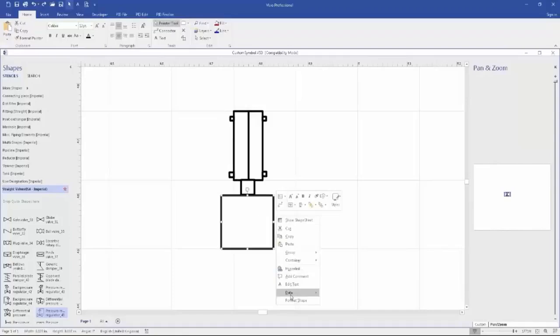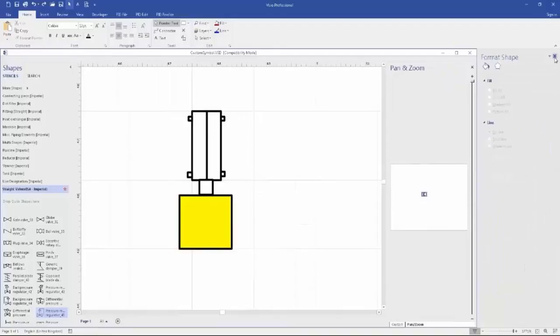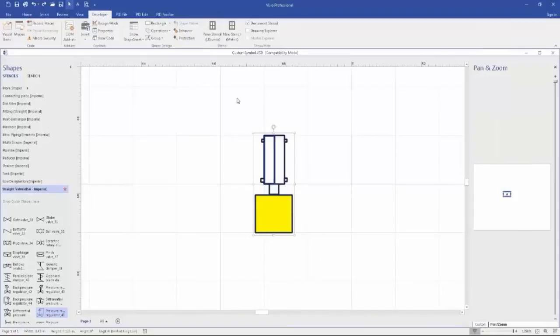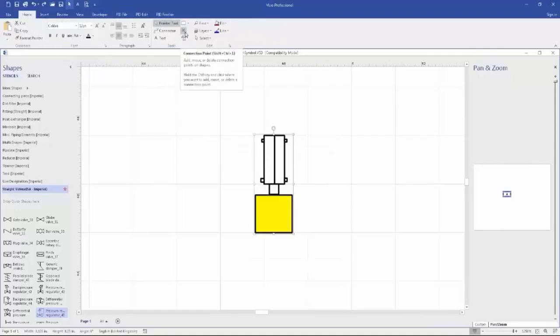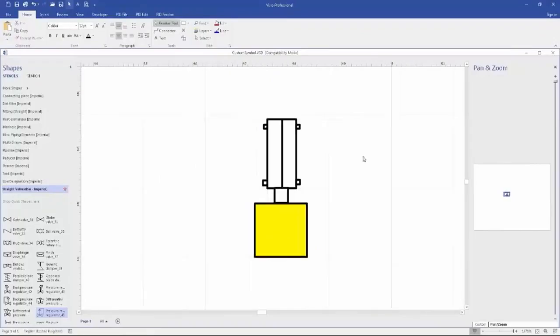These objects created with new symbols can be used exactly the same way as other delivered objects. Now once the symbol is created, you can group it first of all, and after the grouping, you can define the connection points and insertion points. So for this particular custom valve, we are providing two connection points and one insertion point. This will provide the proper connectivity on the pipelines.